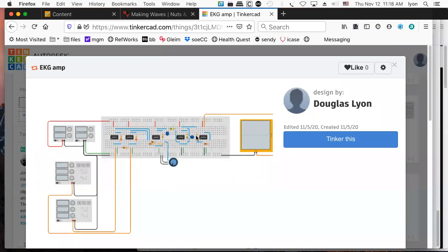You need an amplifier. And it's a funny thing. You talk to these people and you think, oh, geez, they took the microcontrollers course, therefore they know how to digitize everything. But they really don't, right? Because the world isn't 0 to 5 volts. It's just not. And the signals that come off your body are really low level electrical signals. So if you want to play around with that stuff and amplify it, you need things like this, which is, I don't know, perhaps 5 op amps, and amplifies a very low level millivolt signal. And in fact, you'd want to do this so that it could filter out the various waves that are embedded inside of an EKG, the PQRST waves, that sort of thing.